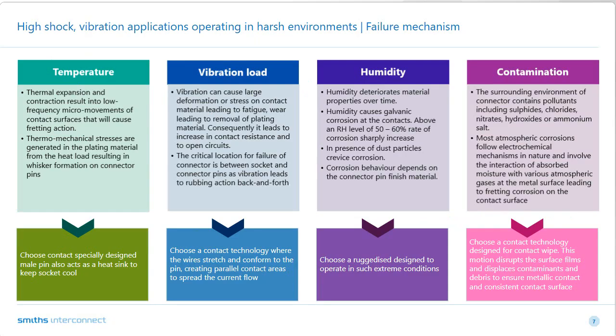Right. Now, I'm not going to necessarily go line by line on this slide, but I really want you to reflect that when we go back to the first slide of 15% failure mode, a few of the things that ultimately contribute where connectors become part of the problem statement are related to one of these four boxes. Either it's due to temperature, or it can be due to vibration load, because remember that often connectors and electrical systems are resident next to very high vibrating equipment.